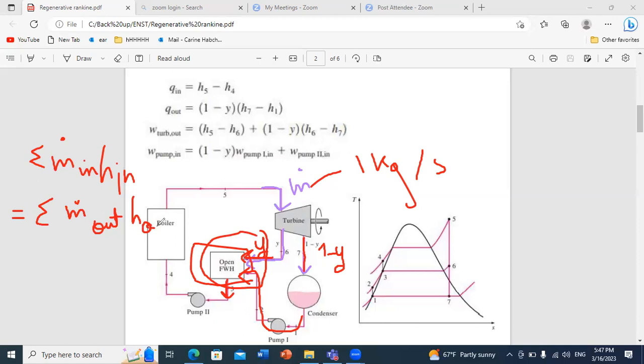Exactly. In general, if you start from the general energy equation, you don't have Q, because when you say Q dot control volume, it means you are computing the heat rate between the heat exchanger and the surroundings. The heat exchanger in general is well insulated. Why? Because what you want is to mix, or exchange heat between two streams.